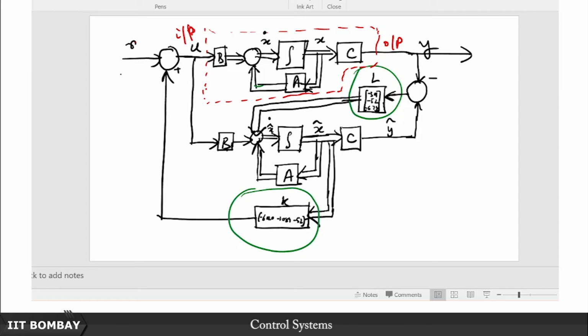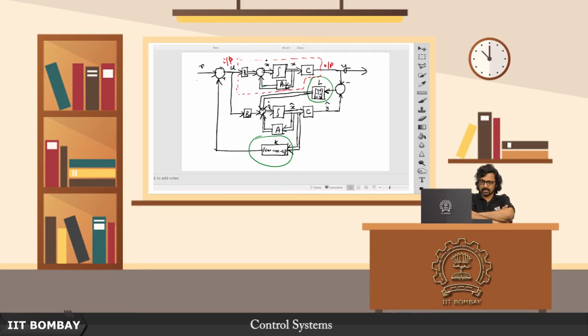So we saw all of that, and then we went over to this interesting new paradigm, that was the Nyquist criterion, where in the same plot you basically can see the phase and magnitude reflected together, right. It was a conformal mapping that we saw, and just by counting the number of so called encirclements and keeping tab of that, we can actually say whether a closed loop system is going to be stable or not.